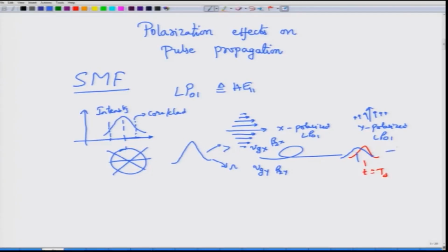But now when you put it through a detector, you want to detect what would be the output, since the detector is only going to look at E cross H, or E cross H conjugate, which if you remember is actually the Poynting vector, correct. And since you are considering scalar variables and transverse coordinates, what this actually means is that you are looking for |Ex x hat plus Ey y hat| magnitude squared. The detector cannot detect the fields, it can only detect the power. What it actually detects is this combined pulse which would then be looking like this.